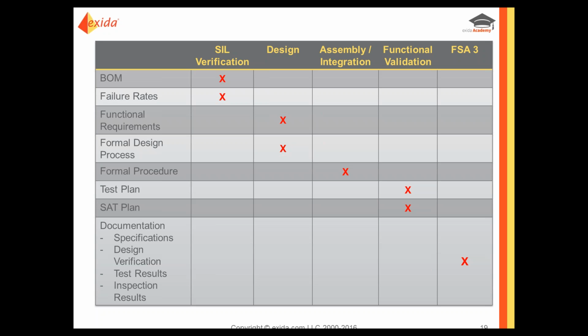This is a very good one, asking: valve assemblies are composed of a lot of components, how do you know which ones are critical? I would recommend doing a failure modes and effects analysis. Basically you're saying, what are all the components in the final element? What's their function?